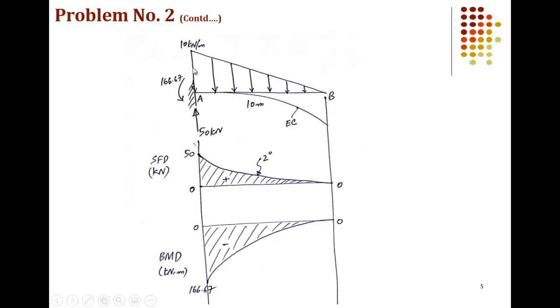For that, we will look at the variation in the magnitude of the load. The magnitude of the load is decreasing as we move in the rightward direction. So the slope of the curve should also be decreasing. So this is the curve with decreasing slope. If you draw a tangent here and mark its slope, you will get a larger value of slope as compared to this point. If you draw a tangent here, it's almost equal to 0.